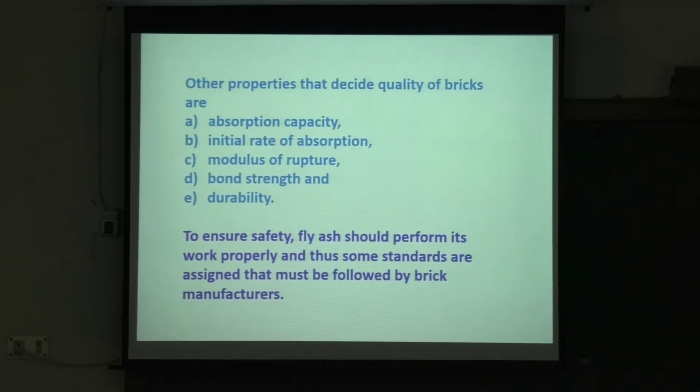We have done a lot of work where we have used carbon epoxy composites as a coating outside the brick walls because they take up energy, whereas bricks take very little energy. If you give the carbon epoxy composites, they can support the bricks. It can hold the bricks for at least 10 or 15 minutes, even under a very high cyclone or earthquake. So that gives a lot of stability. If there is an earthquake, and you have 10 minutes, you can run out, at least go outside.